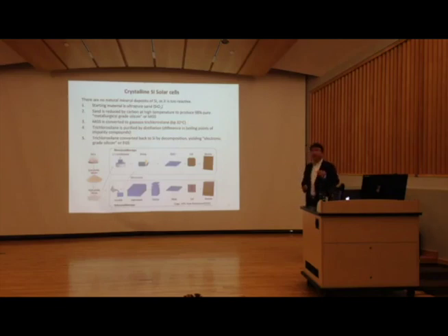If you've ever been to a manufacturing plant that produces polymer, etc., you will see the big distillation tower. Basically, silicon solar cell goes through the same process. They also have a distillation tower to do it. Probably you don't know it. And after that, you have very high quality silicon, we call it electronic grade silicon, EGS, that's this one. And then you go through this process to get crystalline silicon and manufacture cells, and put a lot of cells together. You should be able to get what we call a module or panel. So that's the way to manufacture solar cells.